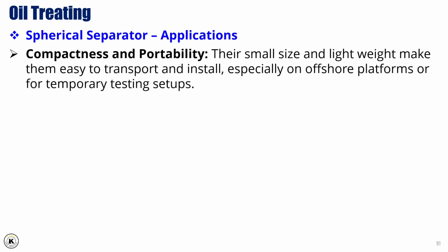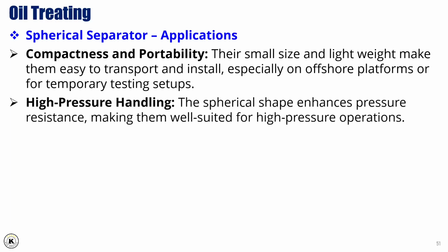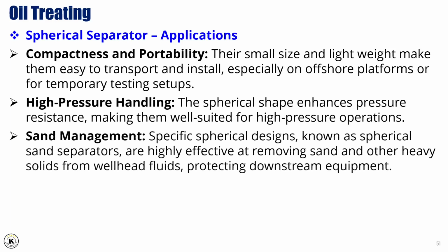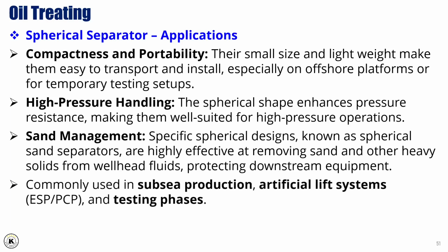In terms of applications, spherical separators are incredibly versatile. Their compactness and portability make them easy to transport and install, especially on offshore platforms or for temporary testing setups. The spherical design also gives them excellent pressure handling capabilities, making them well suited for high-pressure operations. Certain designs, called spherical sand separators, are highly effective at removing sand and other heavy solids from well fluids, protecting downstream equipment from damage. You'll often see them used in subsea production, artificial lift systems like ESPs and PCPs, and during well testing phases, where their compact, efficient design really shines.